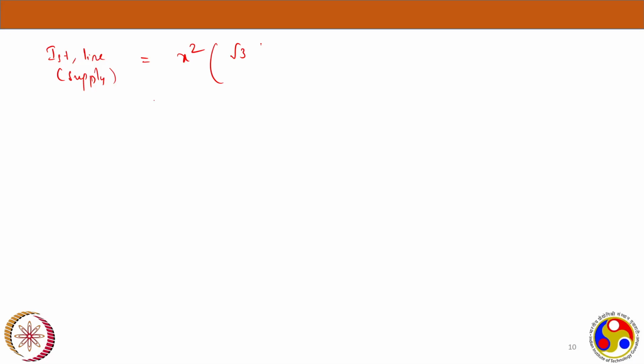Now see, in reactor based starting and also in auto transformer starting, your starting current is being reduced. In reactor, it goes down by the X factor, in auto transformer it is going down by the X square factor. We have reduced even more current in starting. Now let's see the starting torque, how much factor it is being reduced.